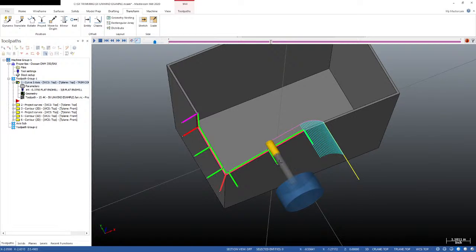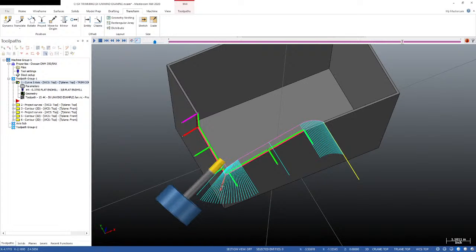Because the vector did not change from here to here, I was able to make a 2-inch long move in my NCI data. If I bump that value up, here's another 2-inch move, I hit the corner and I start stepping around because of the influence of these angled lines right here.